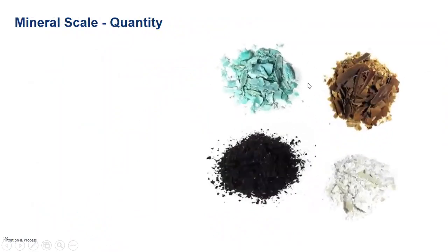So these are 4 scale deposits from a 50-mile radius around St. Louis, Missouri. Lots of different mineral contamination in different wells and aquifers in that region. Geology plays a critical role in what contaminants are dissolved in your water. So what's the impact of that? Well, we measure this based on a parameter called grains per gallon, which is 1 grain per gallon is equal to 17.1 parts per million of that contaminant. Well, 7,000 grains equals 1 pound of rock approximately, very generic.